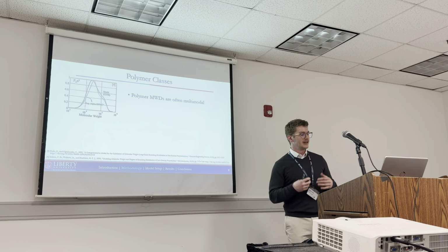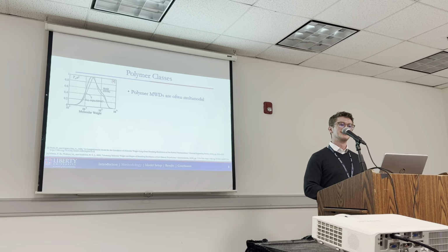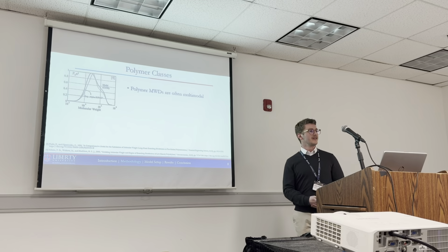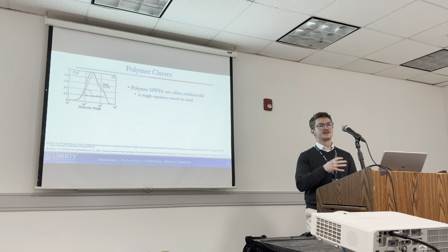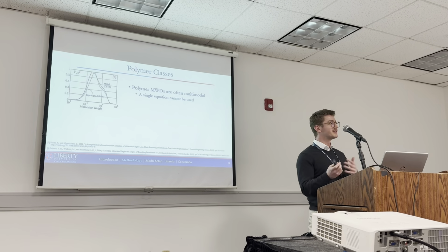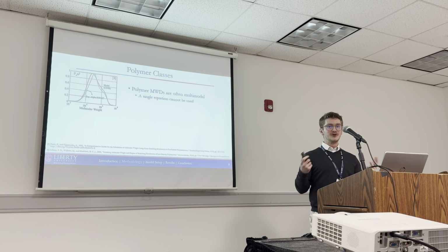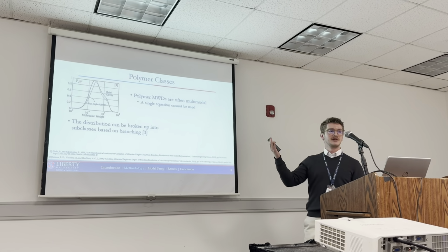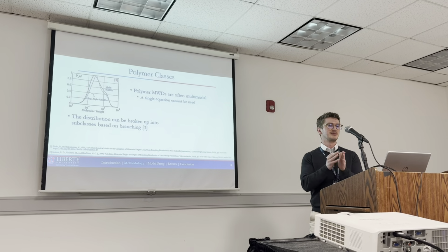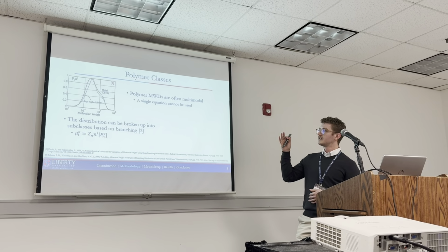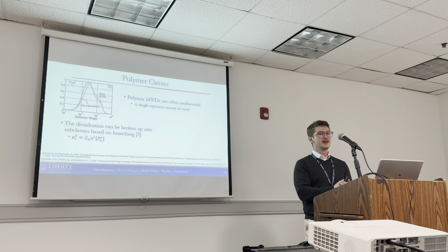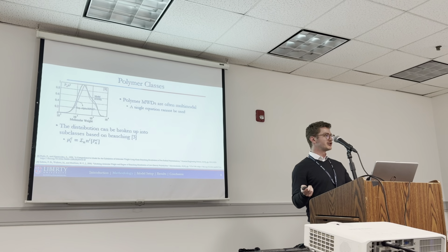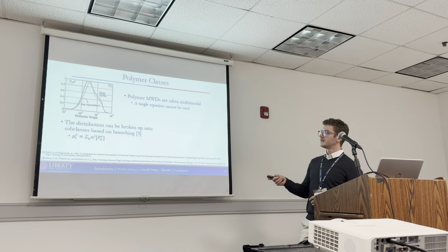Unfortunately though, industrial polymer molecular weight distributions are often bimodal, exhibiting this kind of shoulder here, which is like a second mode in the distribution. And so the process discussed previously can't really be applied because the statistical equations are often unimodal and don't replicate that well. But a technique has been developed to take that distribution and split it up into subclasses where you can have moments for each of those subclasses, which are separated by degree of branching, and that's what's different in this moment equation relative to what I showed you previously, where we just have this C term here.